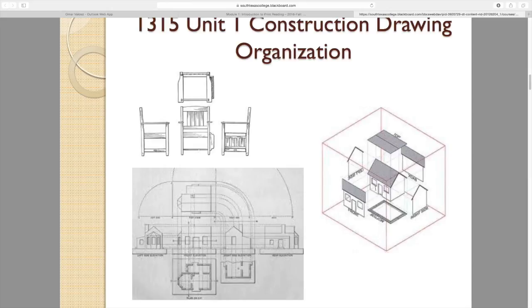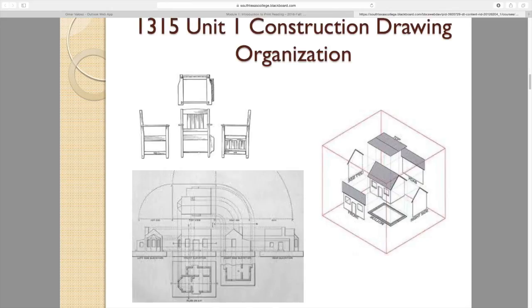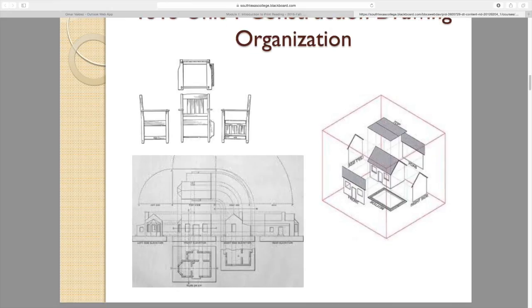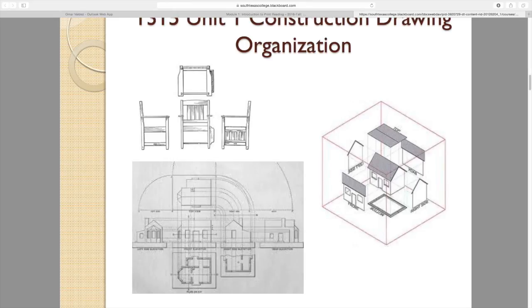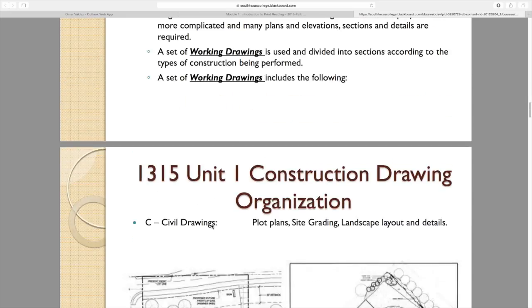This is how it looks seen straight from this side. Notice the roof, how it looks. You don't see any angle. Look at this one. So just projections. The roof looks like two rectangles put together. In reality, they're sloping down, but in the projection, it's just projecting up. Imagine you fly and look down, it's exactly what you see. And you see it here too. These are projections. Again, see how, no 3D, everything's a projection. So this is the orthographic projection drawings.